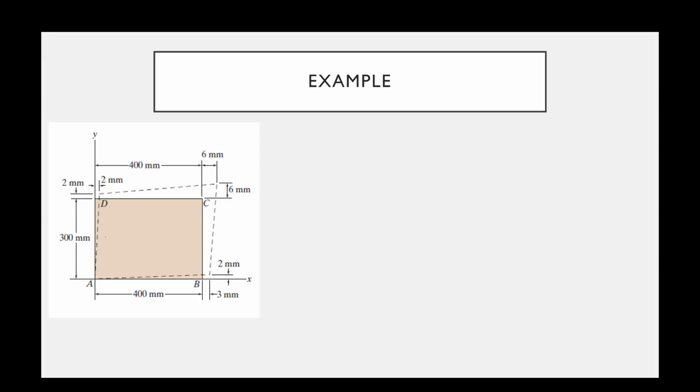we can measure the average strain. Let's say the average strain along line AB. So average normal strain between points A and B. And initially that line was in the X direction. We're assuming small deformations, small change of angle. So we'll say that when we calculate this strain, it's essentially the strain in the X direction.